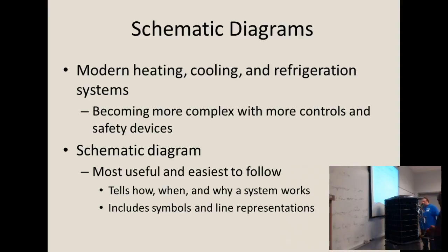One's blue and one's yellow. Y'all look at these. When you see this on your contactor, power goes in one side and comes out the other. So you've got two wires hooking to it. It gives you two connections. If you don't hook it that way, that'd be two powers on the same side. That won't work. One on this side, one on that side, please. On contact, is it negative and positive? Either way, no polarity. It'll work as long as you have 24 common.